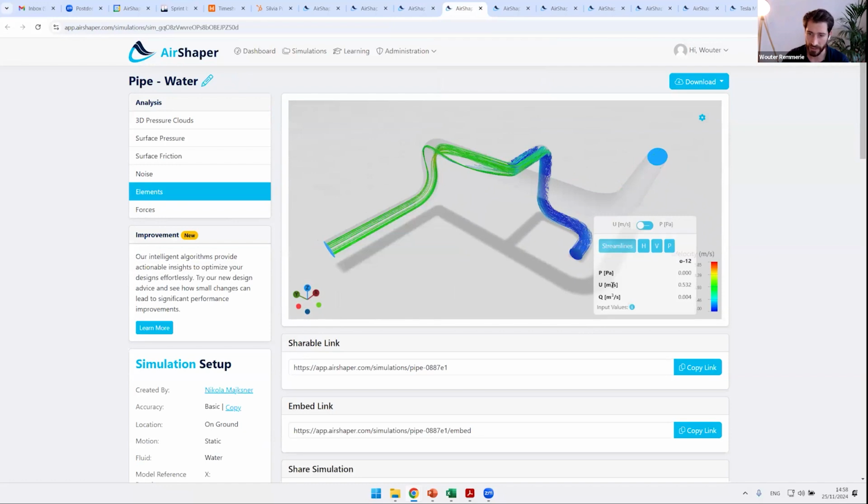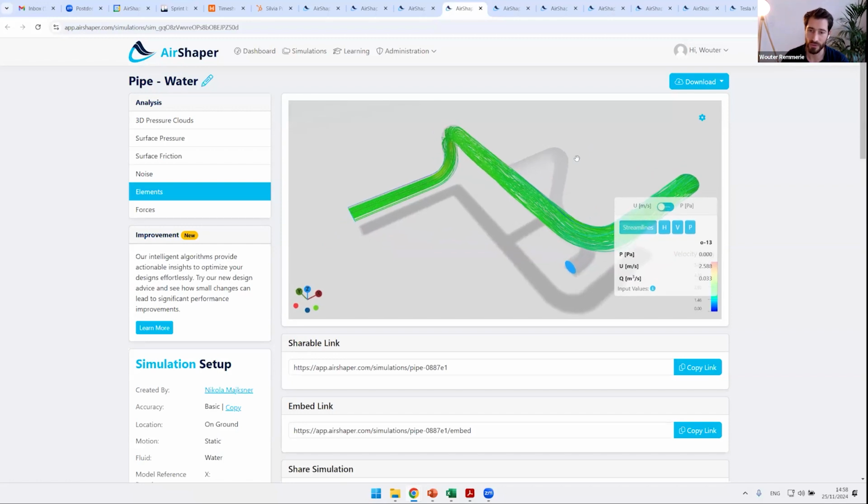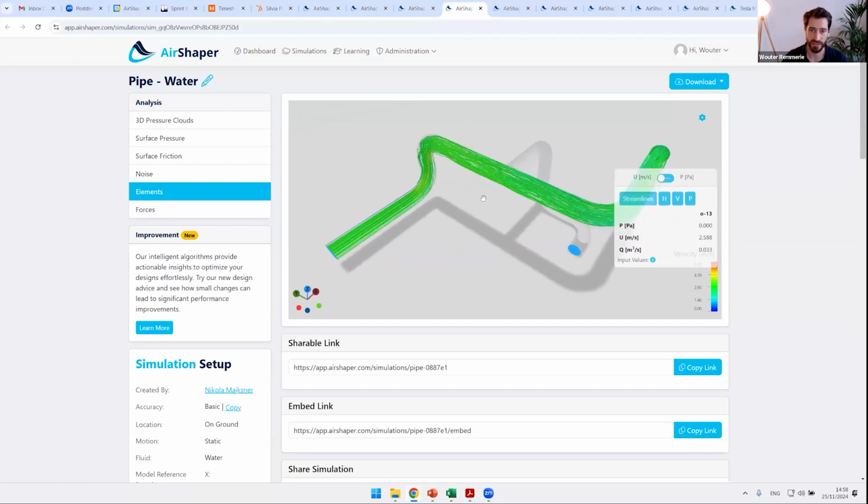It's also about calculating the flow rates and the pressure buildup at a certain opening. Typically, you would have a manifold splitting the flow into maybe 4 or 8 separate tubes, and then you want to analyze the flow distribution across each tube and so on. So automation there really comes down to labeling all the patches correctly and automatically pulling that data and visualizing it for the users.